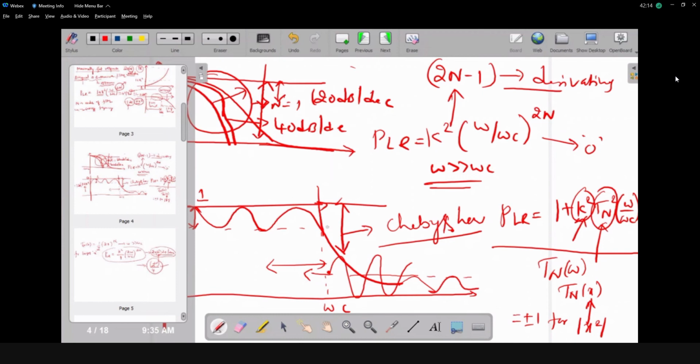That's why the roll off is always much sharper in practical filter design, and they use higher order filters, that is n, 10th order, 12th order, 15th order, like that. Now, the minimum attenuation in the stop band can be obtained using the elliptical filter.